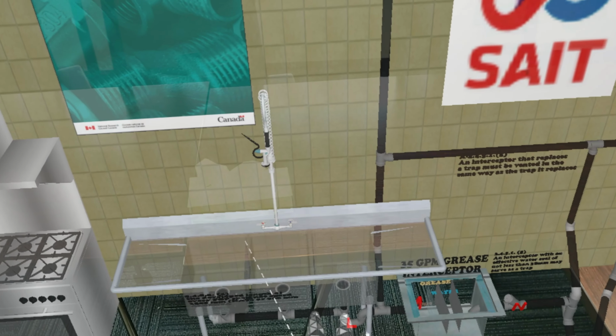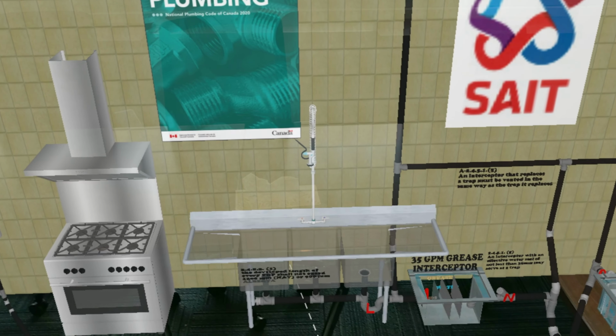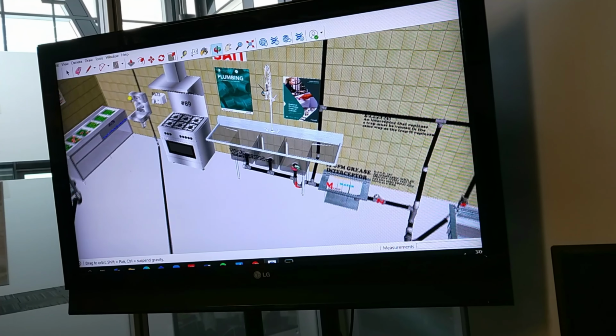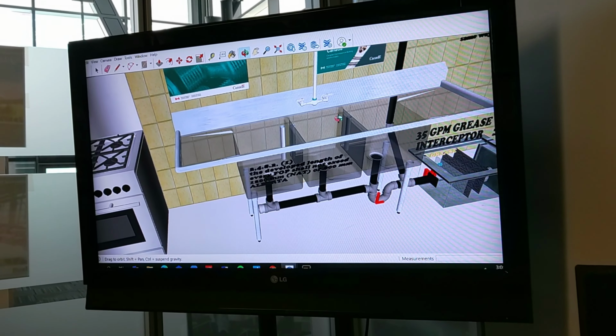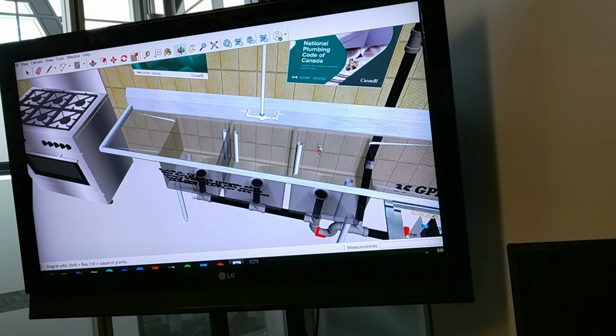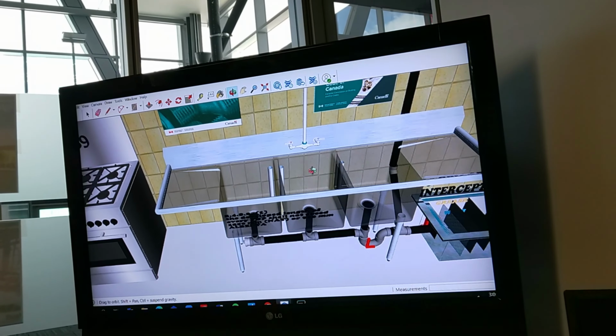So there is something missing from these three sinks. We're going to show you in the code what they should look like for a food prep sink. This has got something in it that the mixed reality view of this commercial kitchen sink didn't have. Here's your food prep sink, and these are what we call non-concealed overflows.